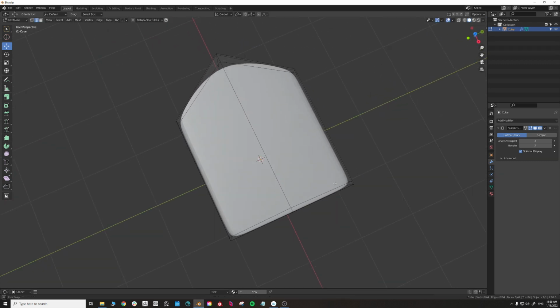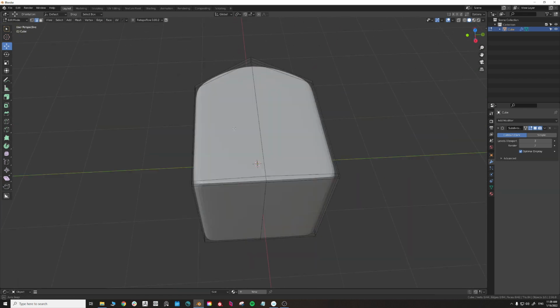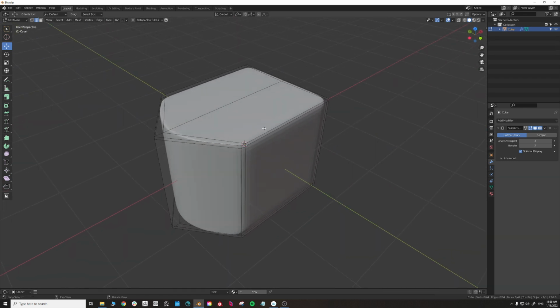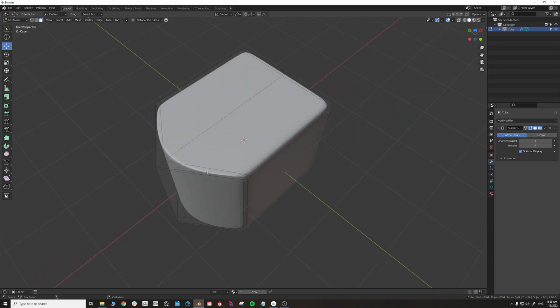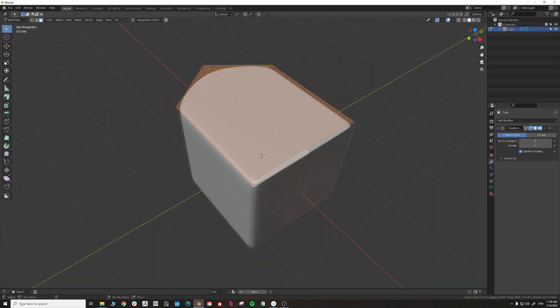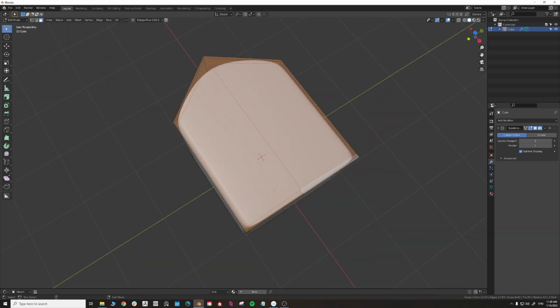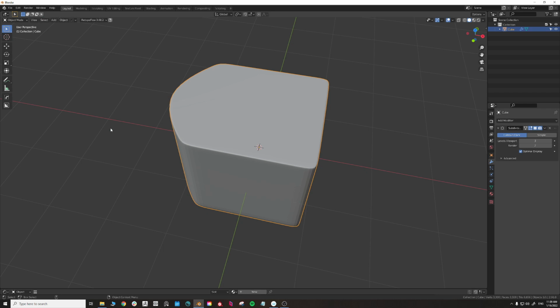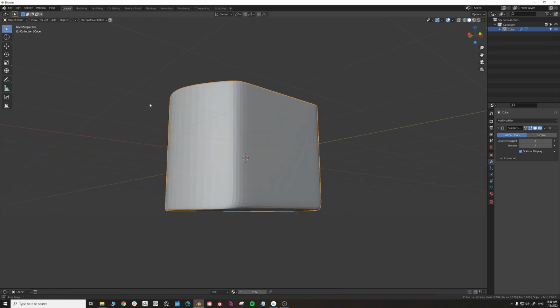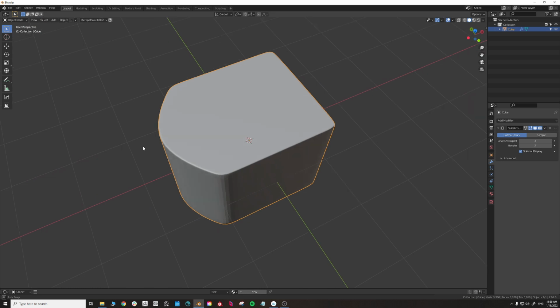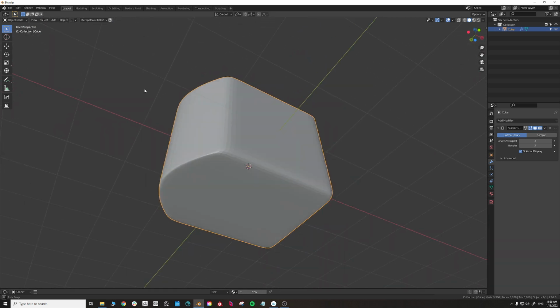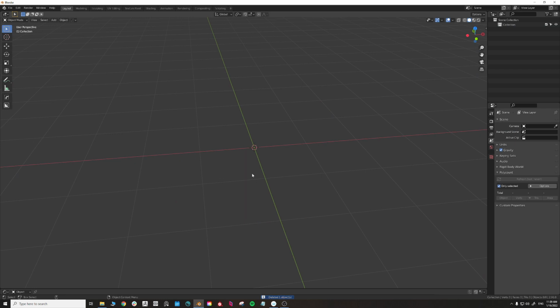And then what we actually want to do is have nice, tight upper and lower corners. So if we go to faces, we can select these and actually inset them. And you can see the difference. Look at how sharp it's become as compared to those that don't have the inset. So insetting things is also another way to add these loops.